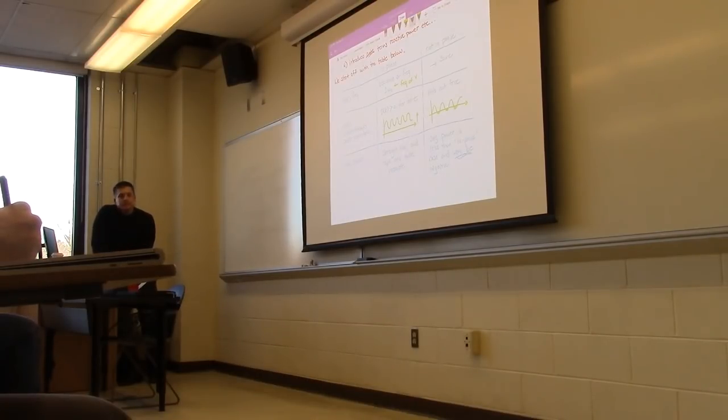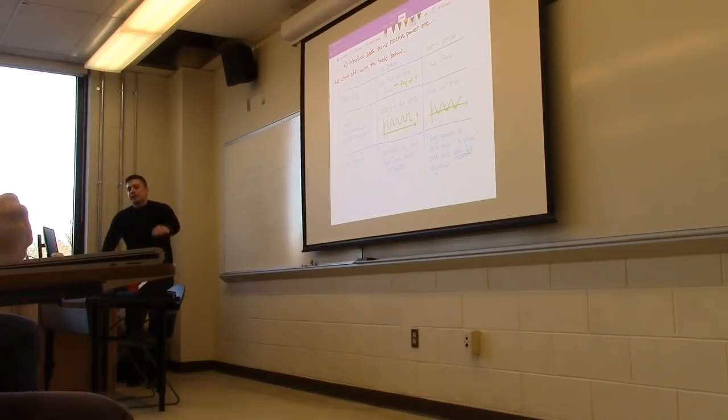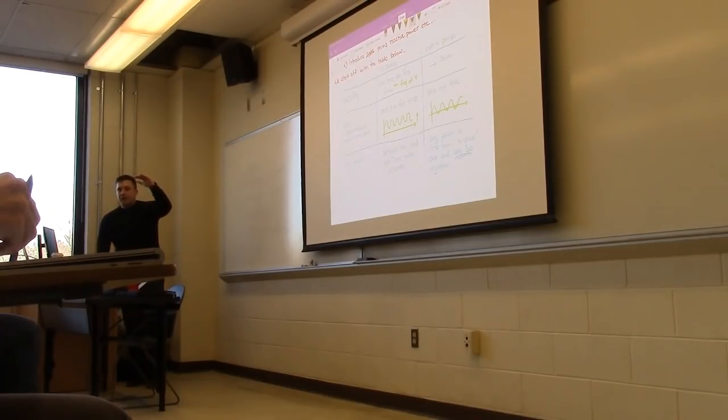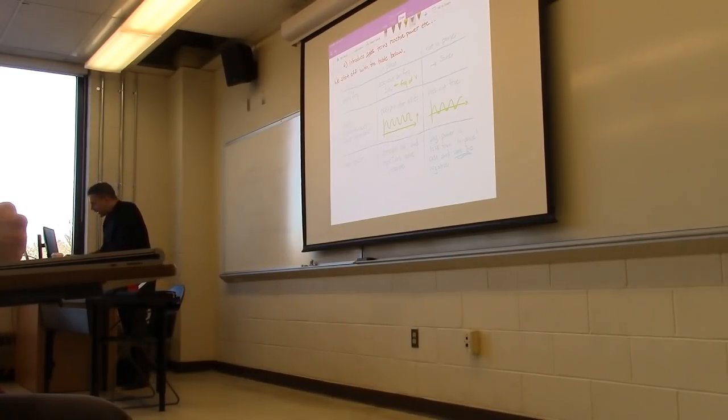And would it be 0 in the case that it's purely reactive, like the average power? If your load is purely reactive, you would have a phase of 90 degrees between your voltage and current. Then all the power will be reactive. Well, we'll get to that in a second. If you talk about it being at maximum positive, you can go all the way down to maximum negative. There is the case where they're completely out of phase, and you end up with 0. Okay.